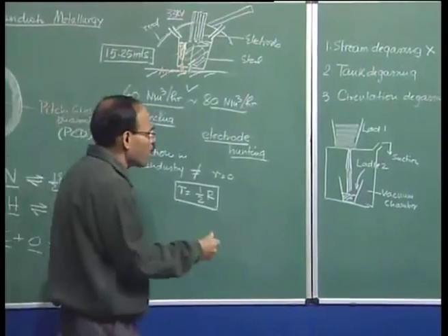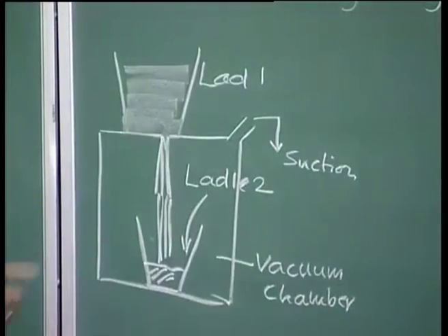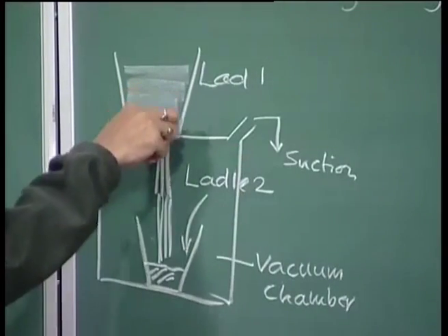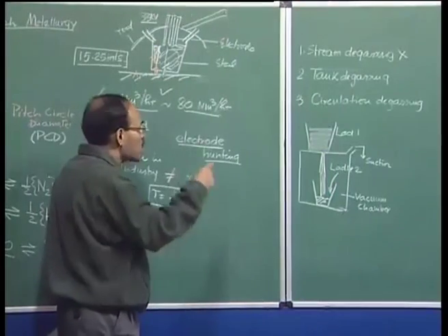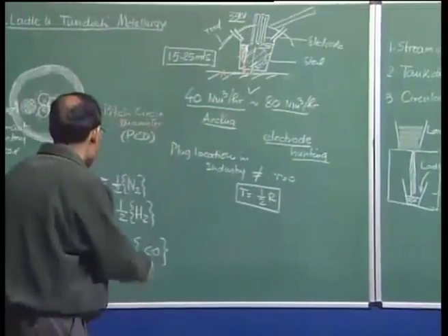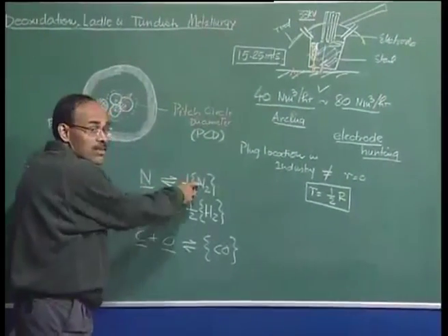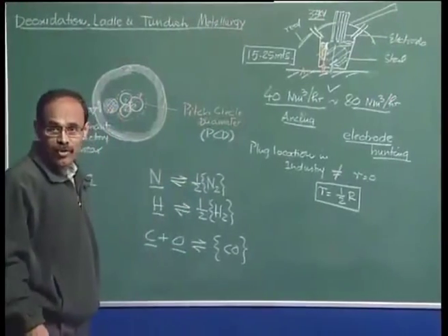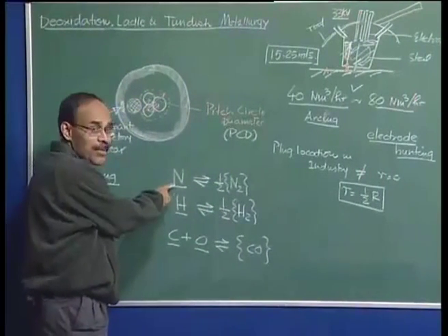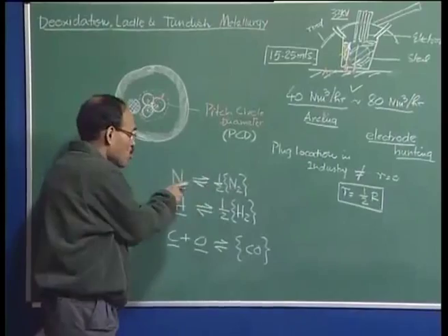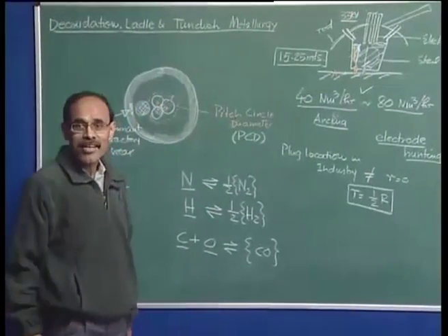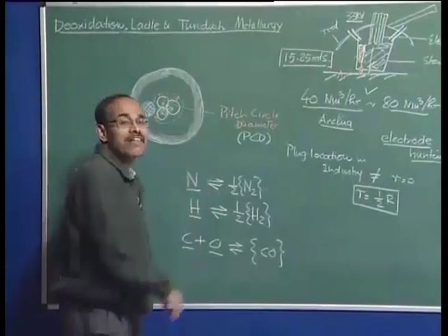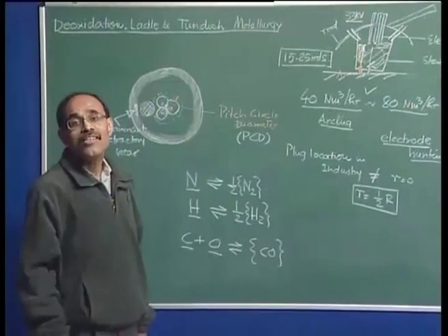So, there is a large formation of droplets as the material falls, and large surface areas are created. These reactions occur at the phase boundary, between the metal and the gas phase. These are heterogeneous chemical reactions, so the rate of the reactions is going to be related to the surface area.